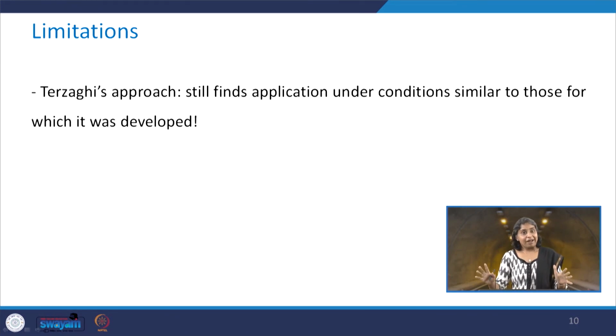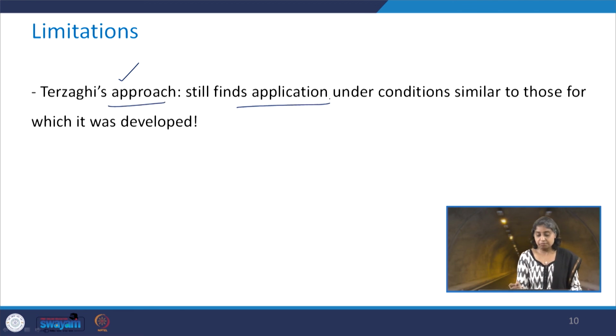So in spite of this limitation, Terzaghi's approach finds its application under conditions similar to those for which it was developed. I mentioned to you that depending upon the size of the excavation, you will be deciding whether Terzaghi's approach will be applicable or not. If the assumptions for which this approach was developed are fulfilled, then Terzaghi's approach can still be applicable.